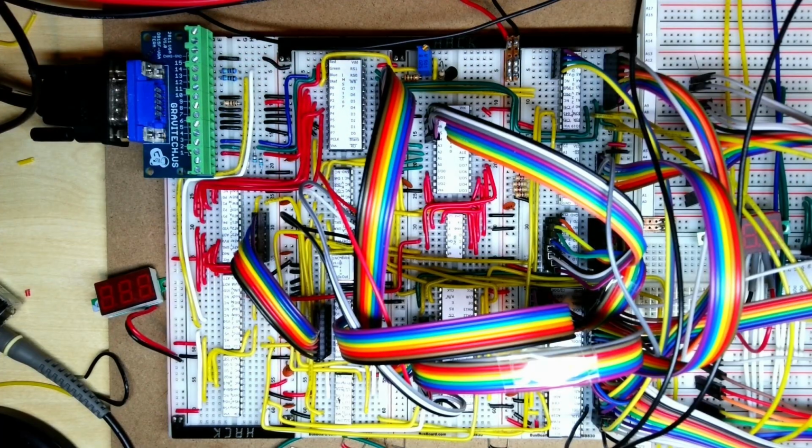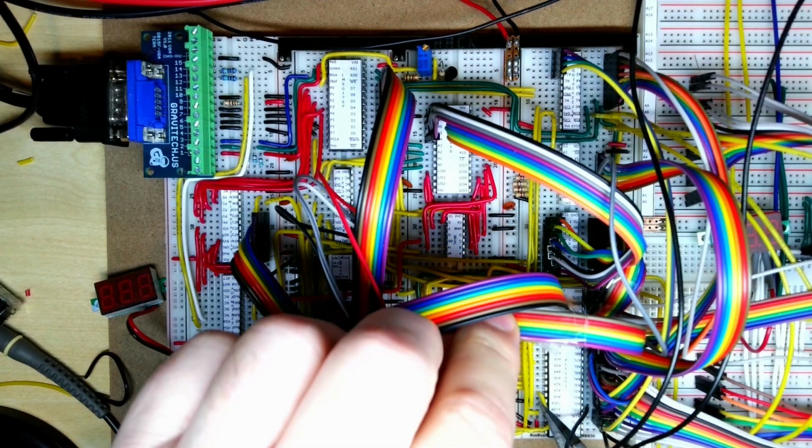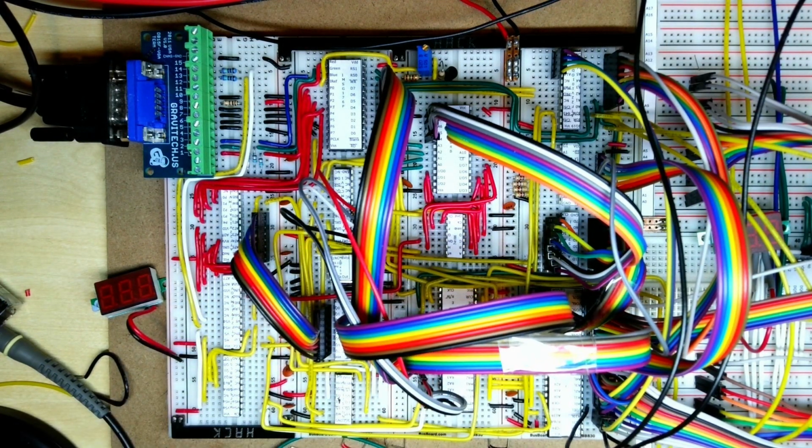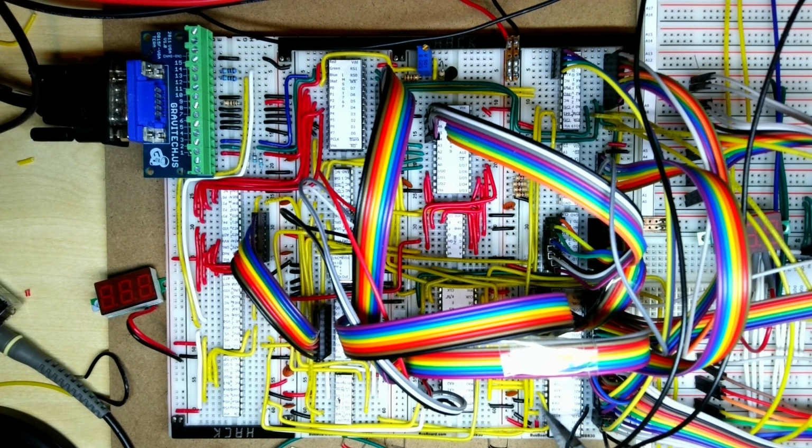So completed wiring up the board, and I did do a trial run, and there were just 2 minor things I needed to change. So I'd missed out the output enable pull down to ground there, and the other thing I discovered was that the A0 address line on the RAM switch between the attribute and the character was connected to the wrong clock. I needed that actually connected to the character clock QC rather than QB. So I've made those changes.